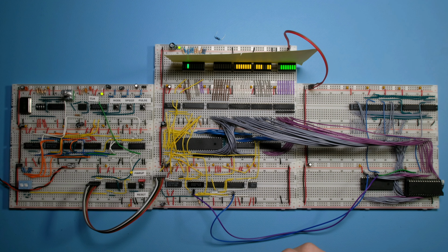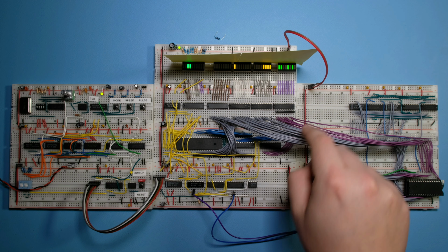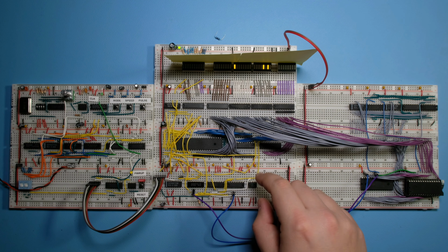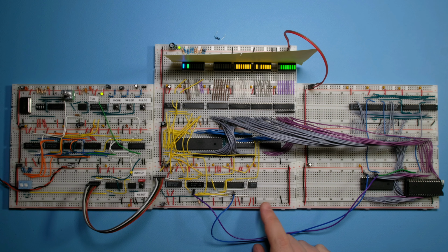So in the next video, I'm going to fix the issue we had with the latch. I'm going to replace it with the correct family. And I'm going to go through all the chips and order the right families, because I think we're now getting into the territory of the timing being critical for a working CPU. So I can't just use whatever chip I have in stock. So I'll go ahead and replace all of this. And then we'll work on the read and write pulses. And we'll make them work with bus enable, ready, and we'll talk about VDA and VPA as well.